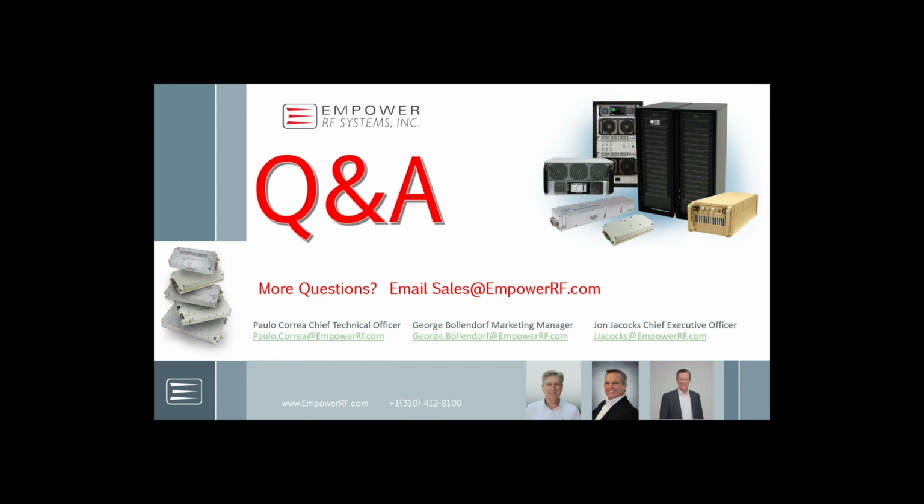Yes, thank you, John, and good morning, everybody, or good afternoon. I don't know where you are. But for me, what we do in Empower is that we add what we call a vector modulator to combine modules or to combine chassis or boosters. We use a vector modulator where we control the phase and the amplitude in a broadband way. That is, a narrow band vector modulator will not solve the problem if you have a broadband amplifier.